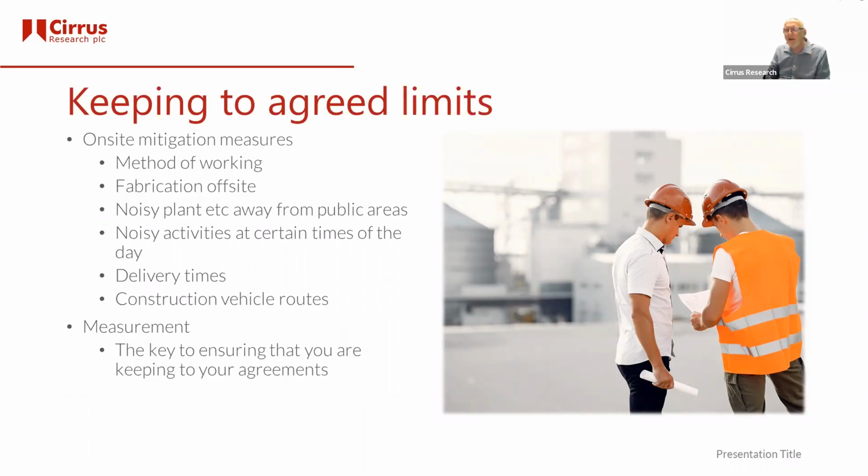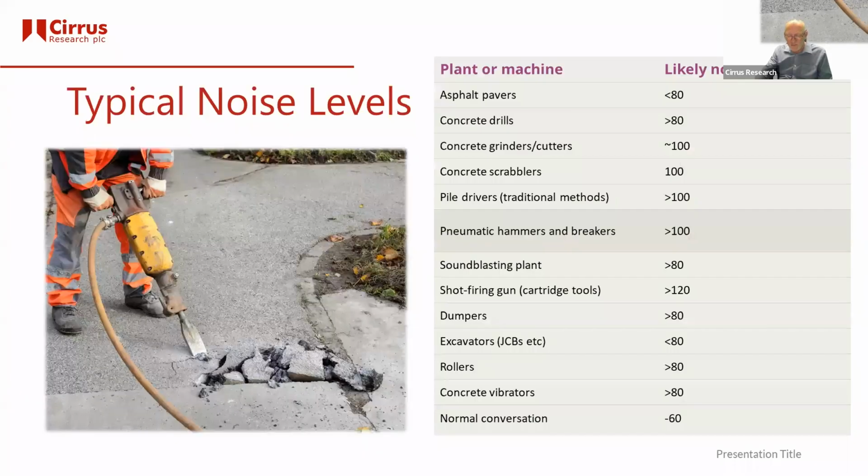Obviously, BS 5228 is a great document for looking at things to do with noise from equipment, barriers, acoustic barriers, boxing things in, placement, all of this sort of thing. And of course, every site is different, so every site will have its own unique challenges. It needs to be looked at very carefully. And the key to keeping to those agreements is really measurement, measuring the noise levels that are exiting the site. Once you've got a handle on that, then you can do a number of useful things with that information.